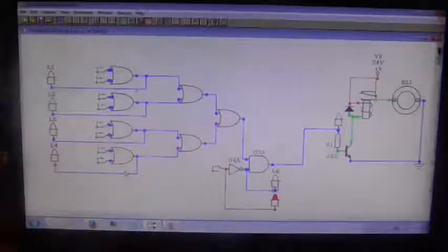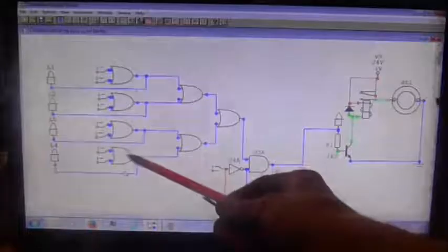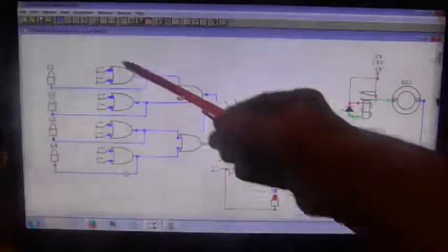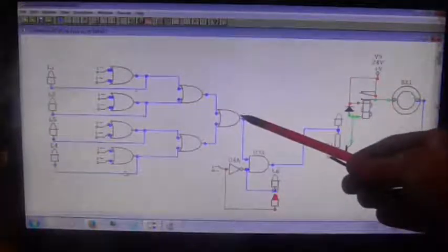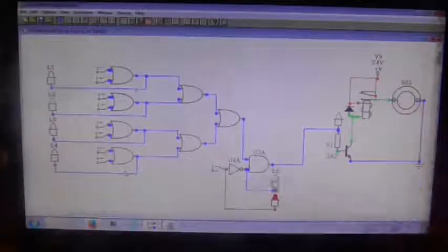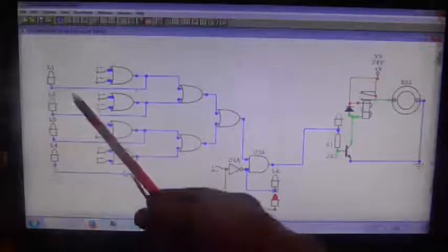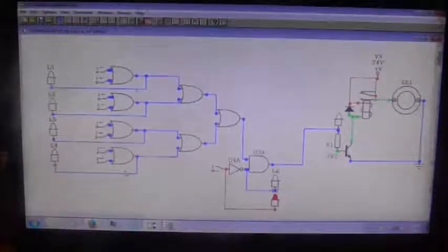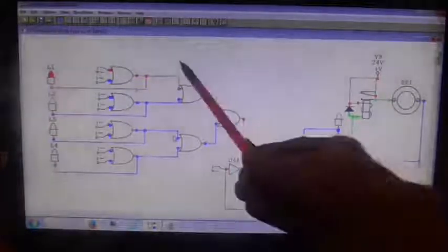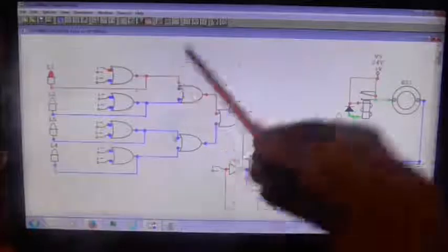So, that's really it for the digital section. And what we've done here is we've taken an OR gate and we've fanned it out so that we can have 8 inputs leading to 1 output. And we've done a test system and we've been able to simulate it successfully using our logic displays and the trace that's built into the package.